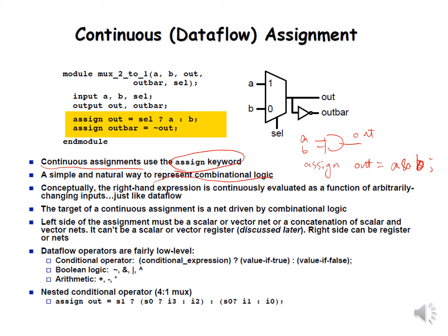Conceptually, the right-hand expression shown here and here is continuously evaluated. Meaning, whenever input A and B or the select changes, it evaluates and updates the output.